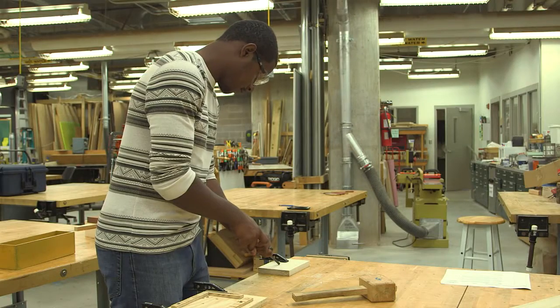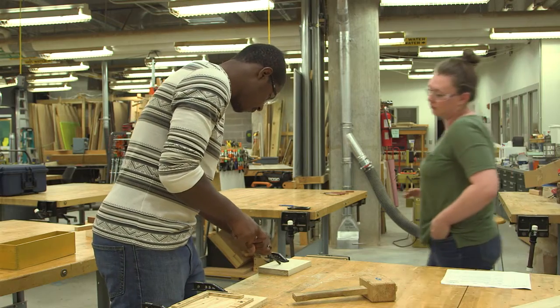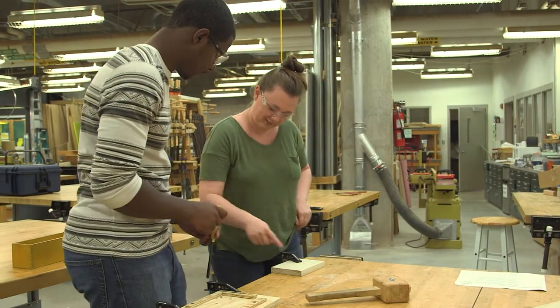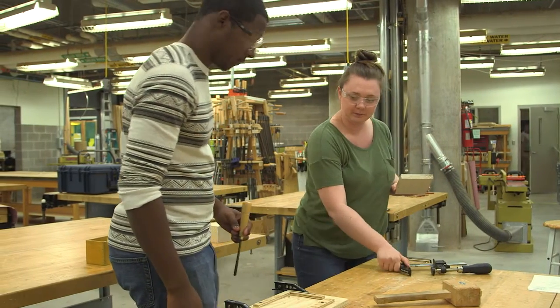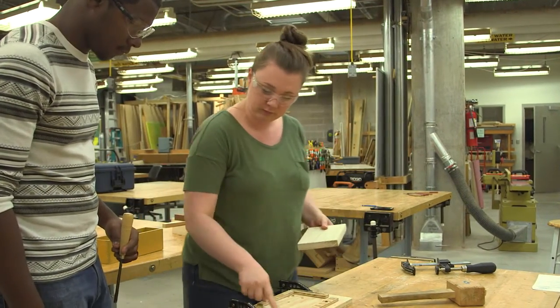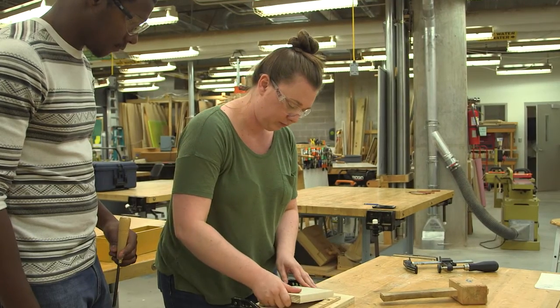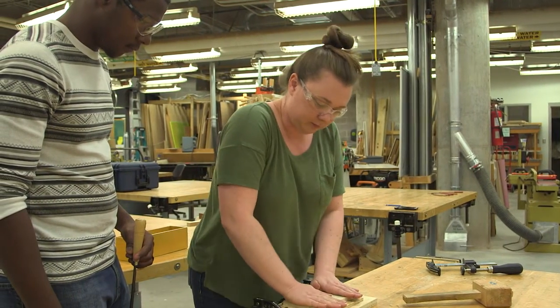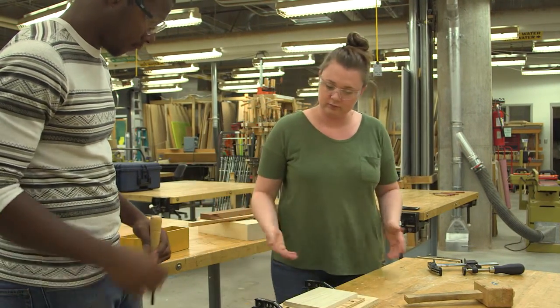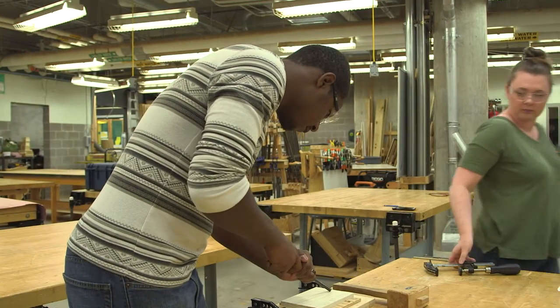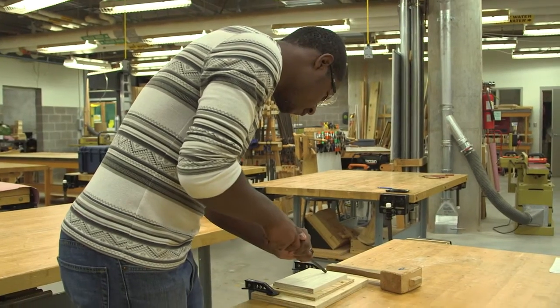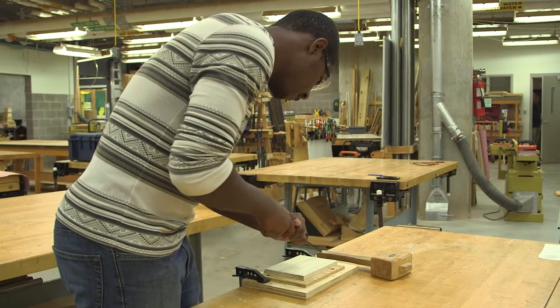You can use clamps to secure your piece to the workbench. Be aware that if the tool slips and hits a clamp, it would likely damage the tool. So, make sure that if the clamp is anywhere in the direction that you're carving, a different type of hold down or wooden spacer should be used. The shop staff can help you create a hold down by using several pieces of material to trap your wood in place.